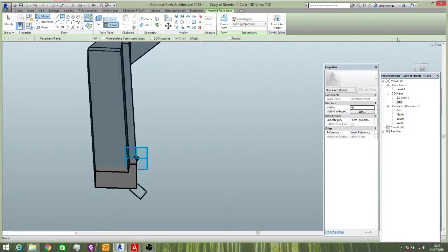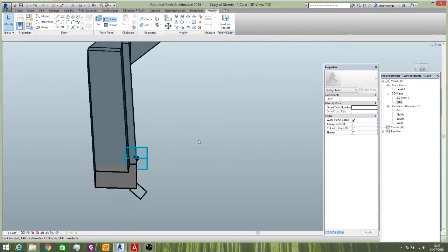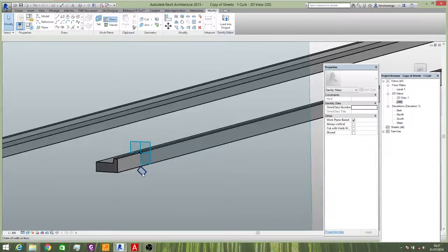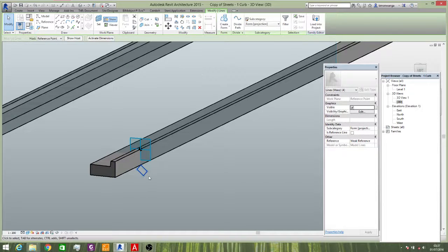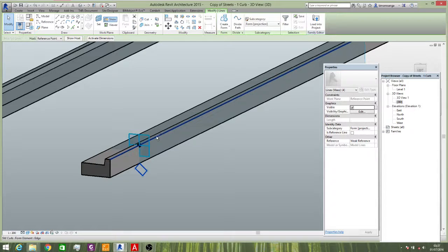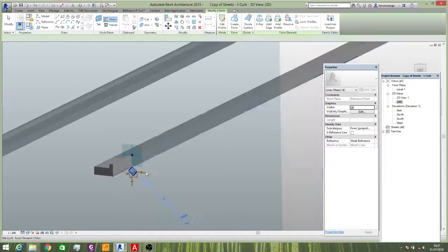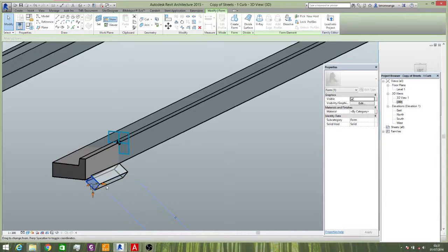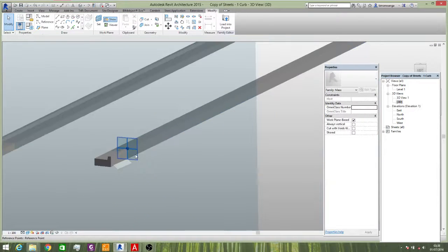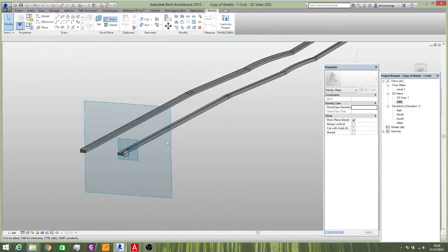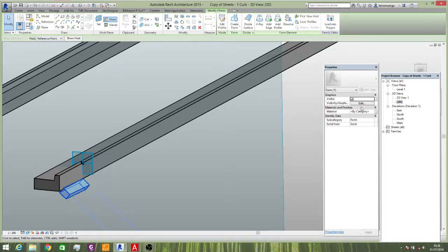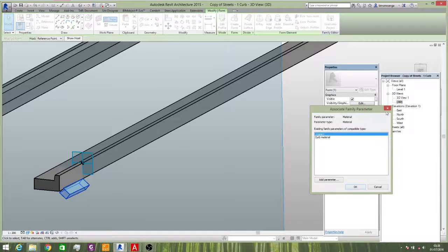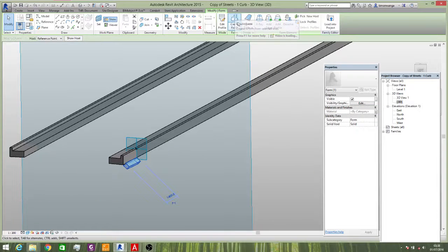And for the first time, just say okay to something funny, so that we simply see what it's like with this tool here. So we select that form, that sketch, and that line, and create form. Now you can extend the form, or if you select a continuous line, then it's supposed to select it all the way, and then maybe you can add material to it so that it becomes a different form, like a drainage channel.